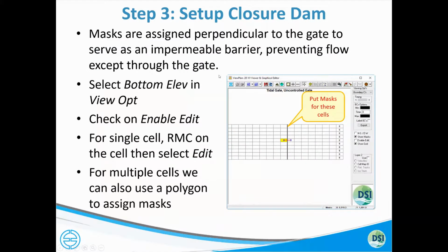So now we have this river and all the cells are connected, so we need to build this dam so that we can prevent flow from moving through this structure that we are assuming is in the middle of this river. To do that, you could disable a row of cells if you wanted to, but these are 200-meter wide or long cells, and it may not be physically realistic to do it. So we're making the assumption here that there's a thin dam, barrage, something